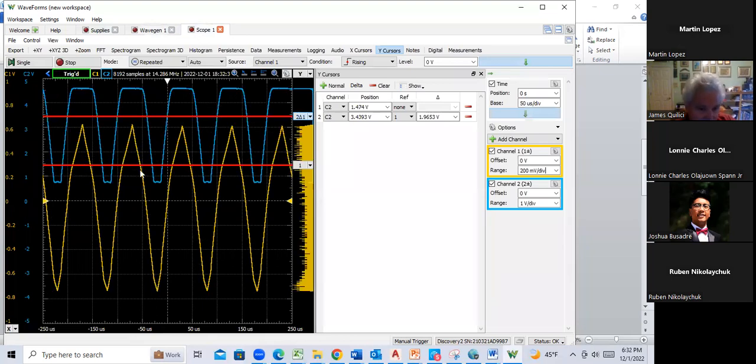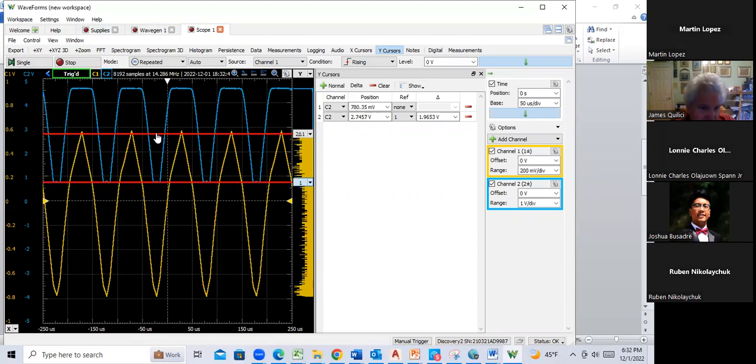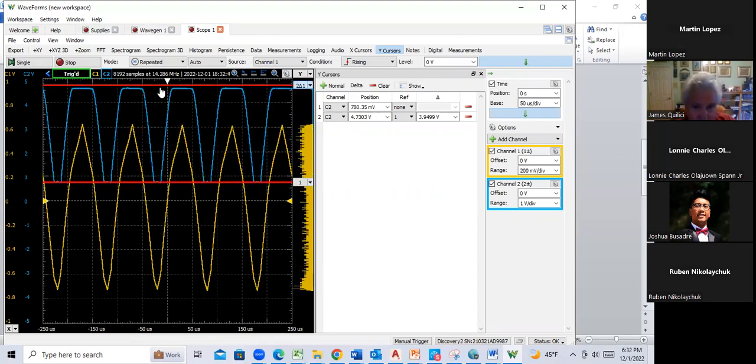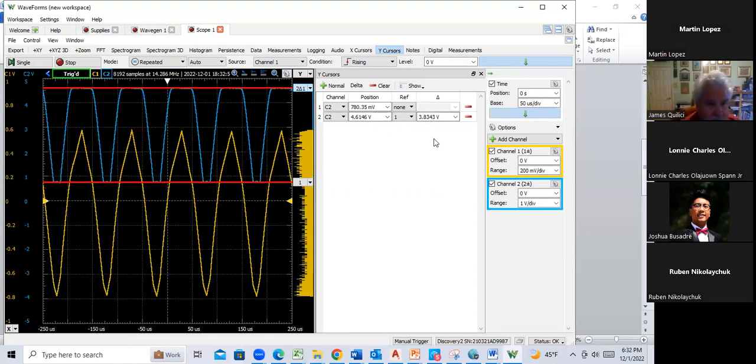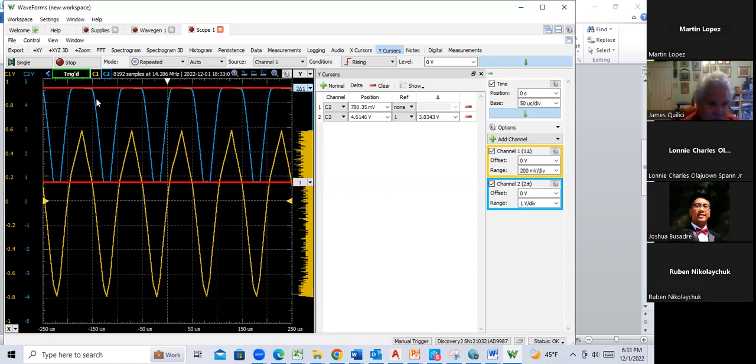Okay, so my dynamic range at my output is basically, I can go between 780 millivolts, which apparently is where my emitter is, and then 4.6 volts at the top end. So I can get a delta of like 3.8 volts peak to peak. So that's what we would call the dynamic range. And yeah, it's clipping harder. It's not necessarily symmetrical here. It's clipping harder on the positive end.